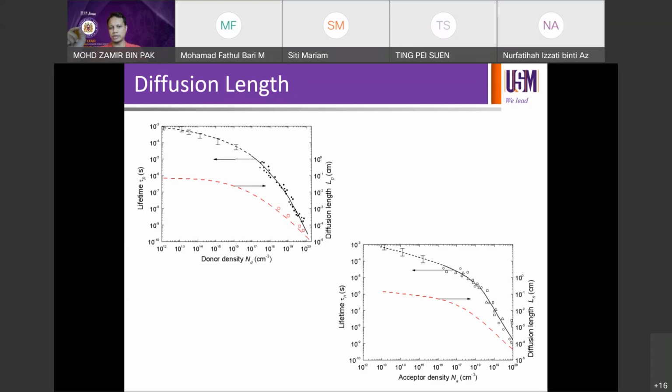You will see that when you go for heavy doping, you compromise your lifetime, but you get a conductive layer. On the other hand, if you move to a low doping level, the layer is going to be resistive, but you gain your lifetime. But it's going to be electrically resistive, which also kills the device. So that's a trade-off that you have to understand when designing a device.